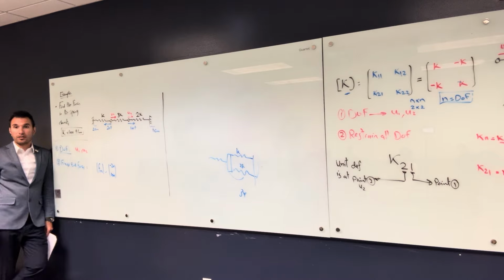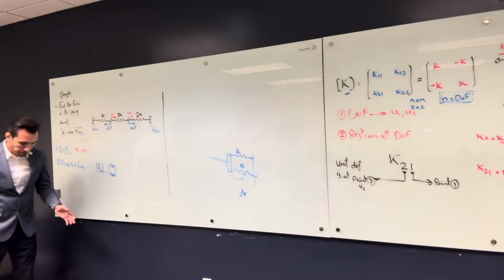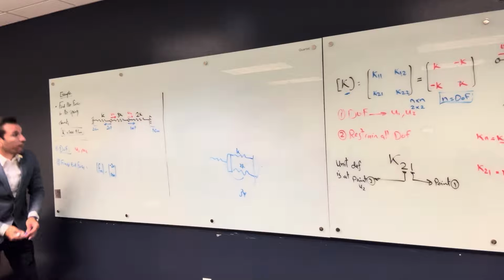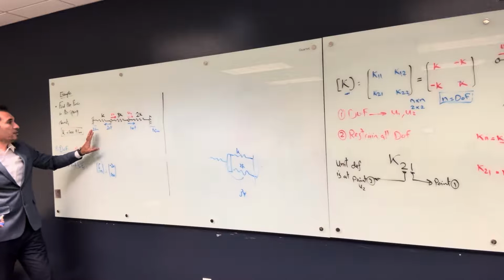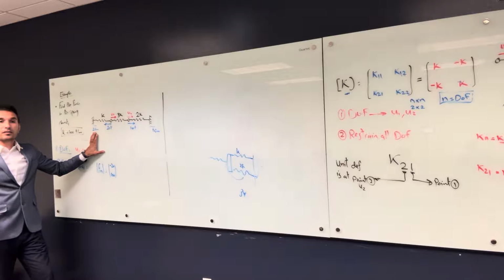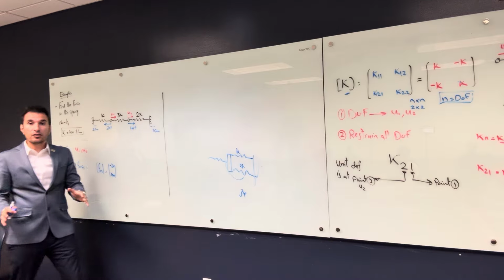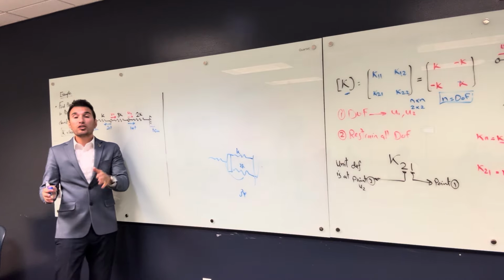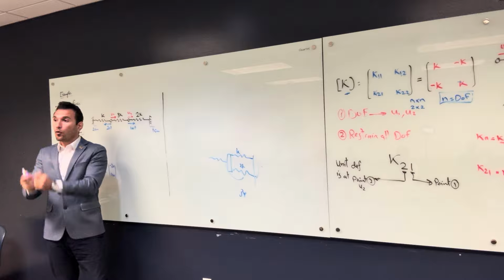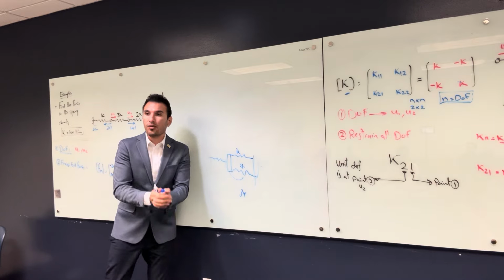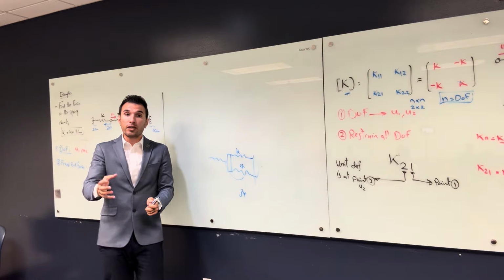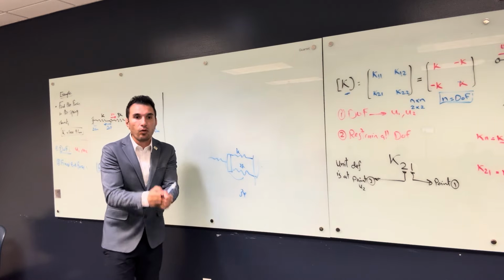How about the fixed end forces? The thing is, what are these? 2 centimeters and 1 centimeter. By the way, these are settlements, and when settlement happens in the structure, that's a load. Load can sometimes be a direct force, and sometimes a settlement, like your foundation going down. Rather than giving you the load directly, I take the whole foundation down.